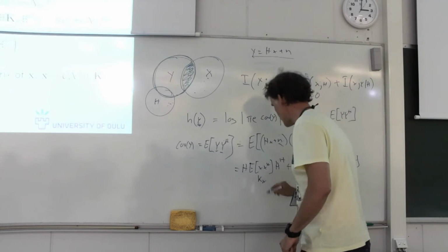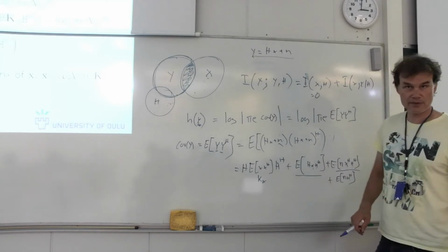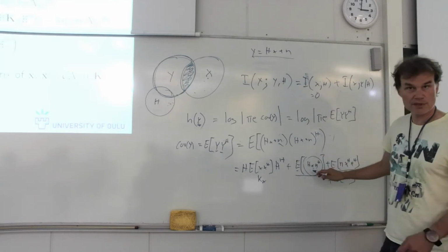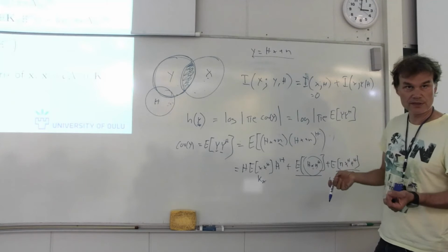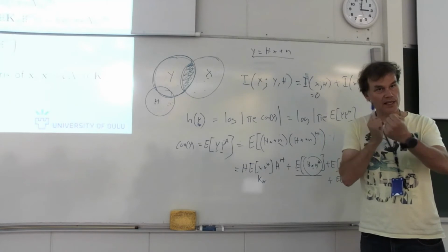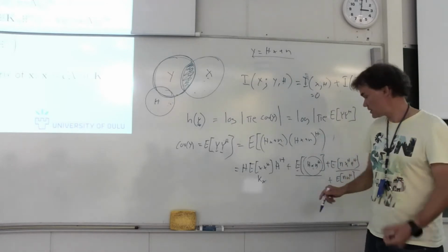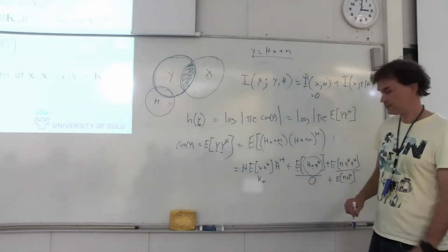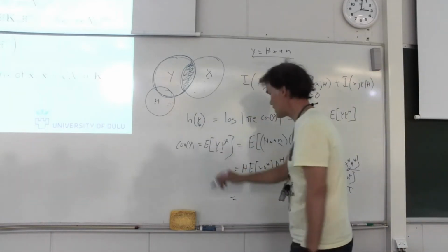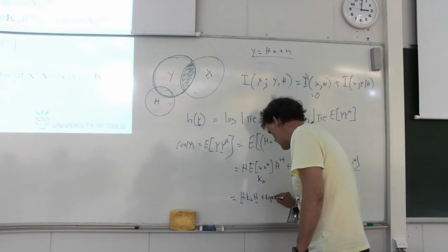Okay, we can call this covariance matrix of x, Kx. What about these cross terms? x and n are independent. So when we take the expectation, this is a rank 1 matrix, Hx times n Hermitian. But now since x and n are independent, when you take the expectation of these random rank 1 matrices, the expectation is 0, right? So the covariance of y is simply H Kx H Hermitian plus N0 I.